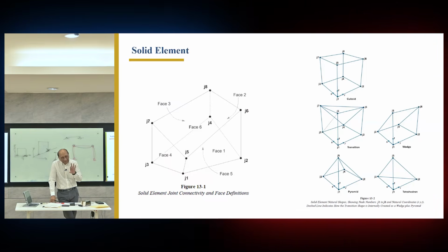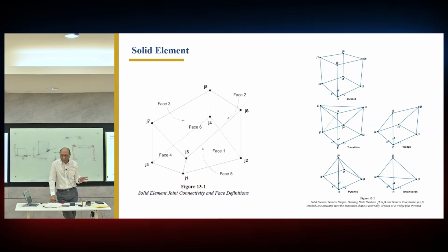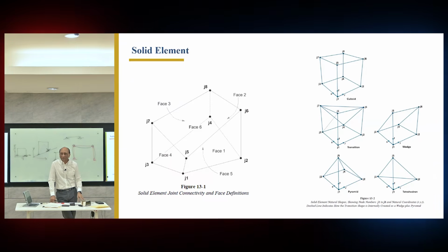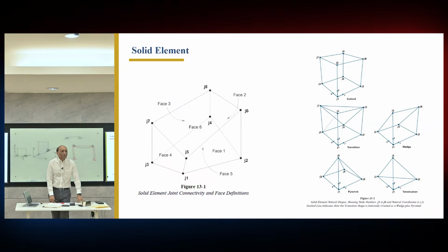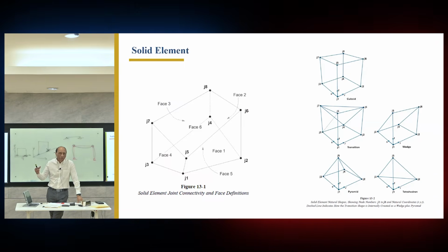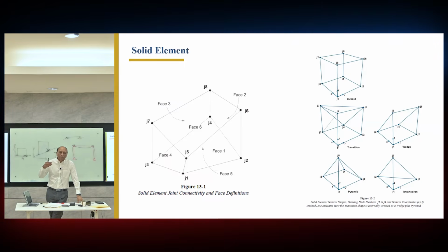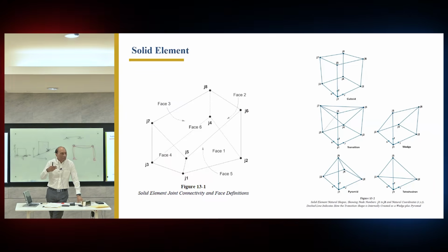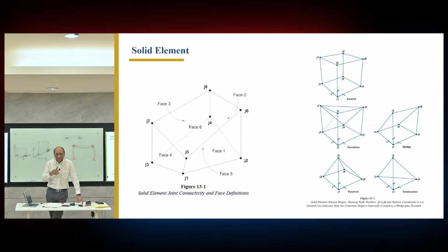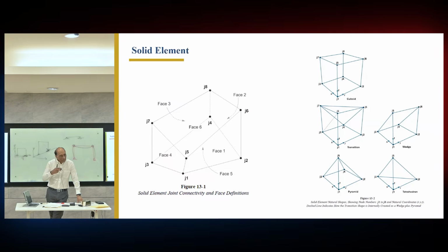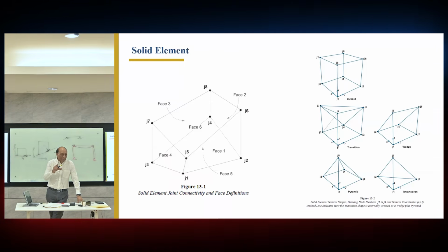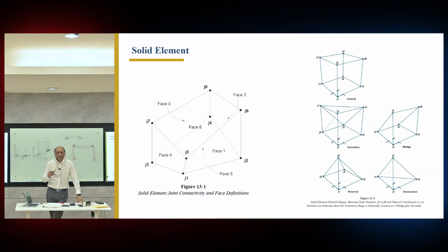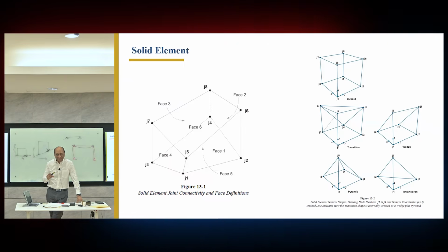They spend more time optimizing those elements rather than creating more elements, because as you add more elements, you get into trouble of meshing, of connecting, of getting the results, and of compatibility. So they decided not to go that way. Just very few basic elements: one frame element, one shell element with 4 nodes, and one 8-node brick element.